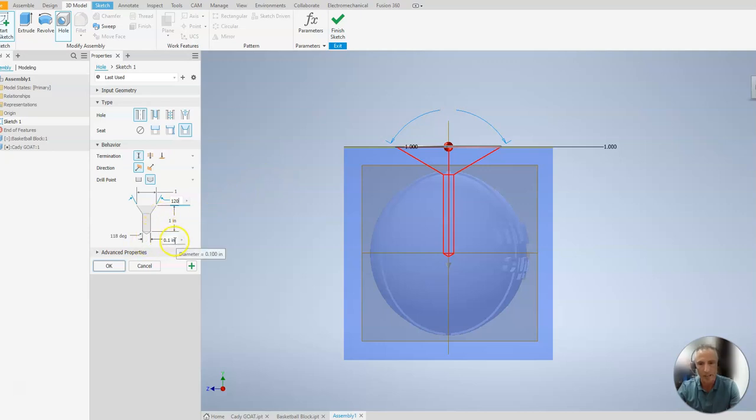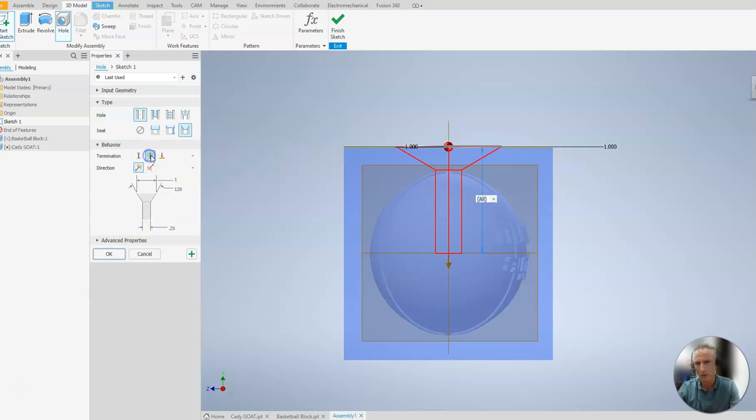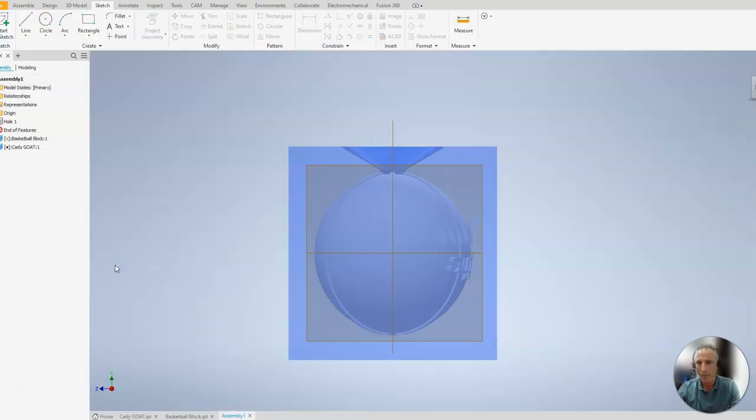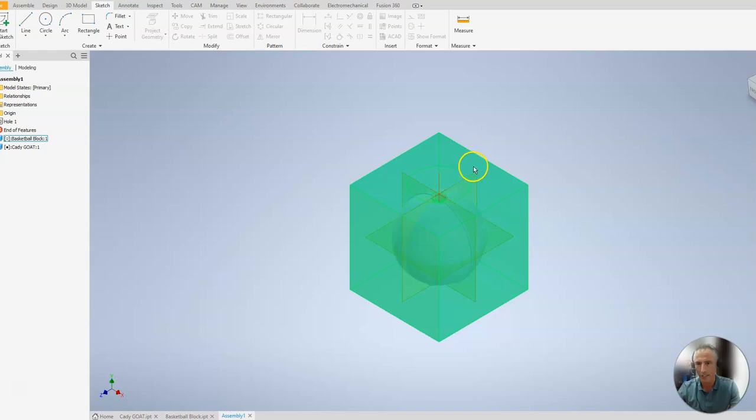The diameter of that hole, chocolate's pretty viscous, so you're going to want to probably use a 1/4 inch hole or so the chocolate actually goes down into it. Now, sometimes it'll default to where the hole is going through the entire object. You don't want that. You want to put distance, and 1 inch is fine. That'll get us into the cavity. Remember, there's not actually anything there. It's going to be a hollow in the shape of a basketball. So that's what you want. And we'll hit OK. Now we have this spout that is a funnel that feeds down into it.